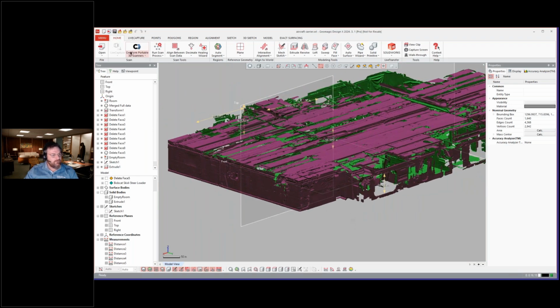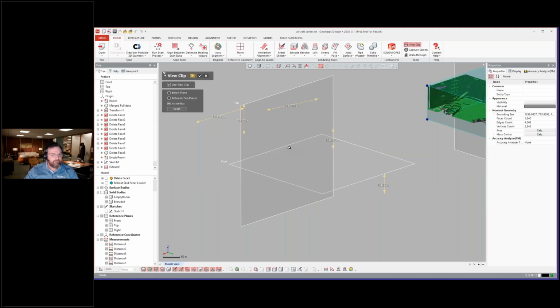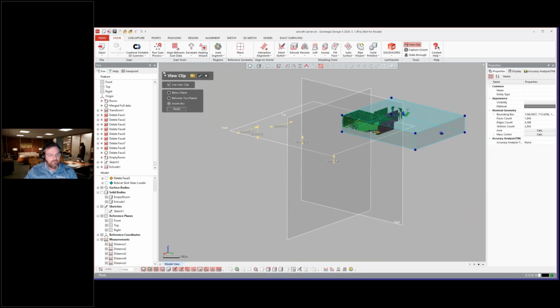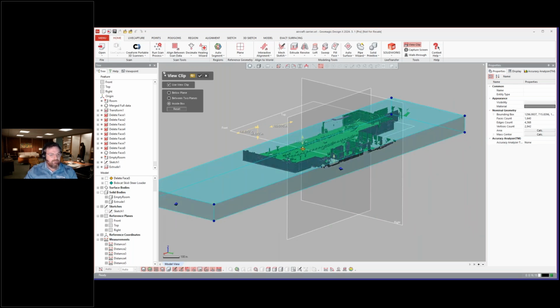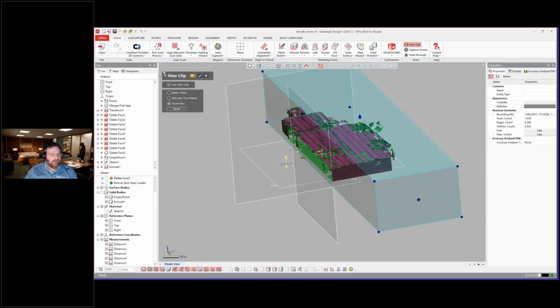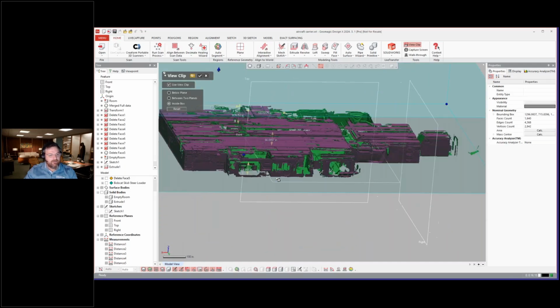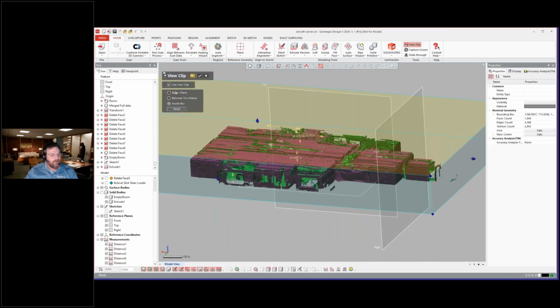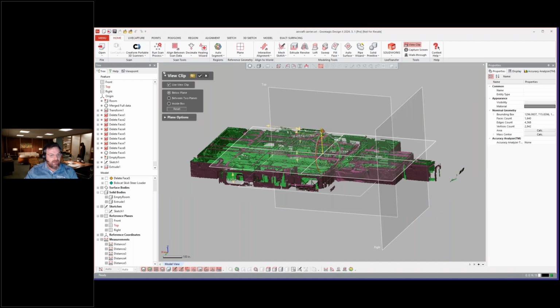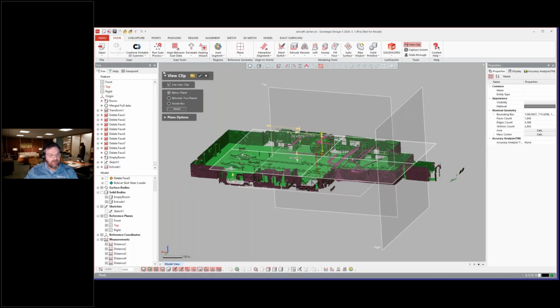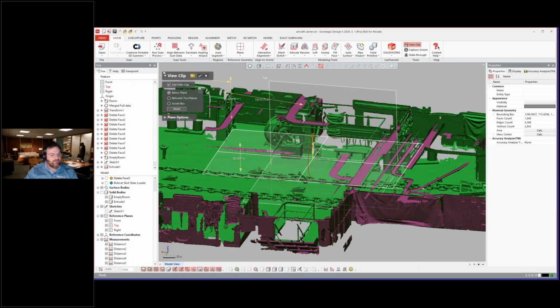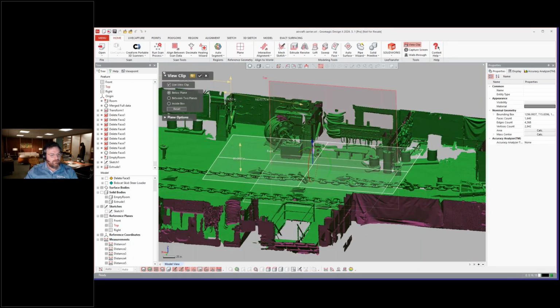Another thing that you can do that sometimes people don't understand is we do have this other thing called View Clip. It's remembering the last one that I did the other day. So we'll go over here and we'll just expand it back up again. This is just going to show everything within that bounding box, and I can set that bounding box a whole host of different ways. If I say below plane, you'll see here I can move this and rotate that around. So if I just wanted to knock off the roof and drop this down, I can do so there.